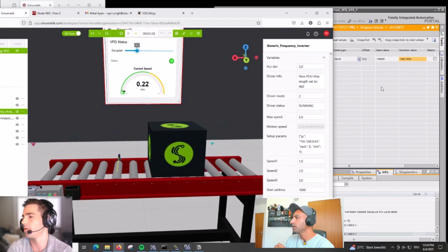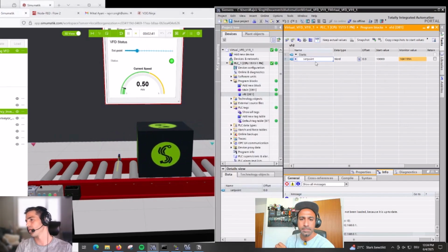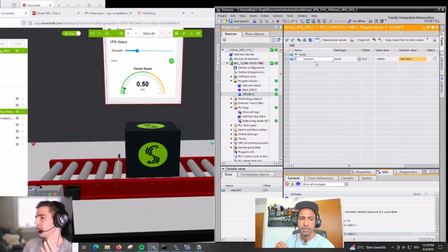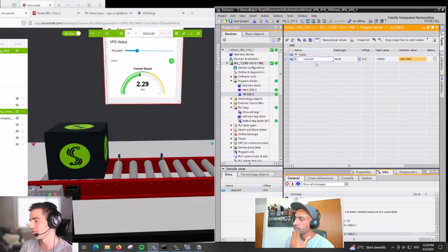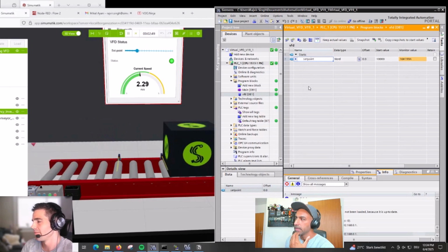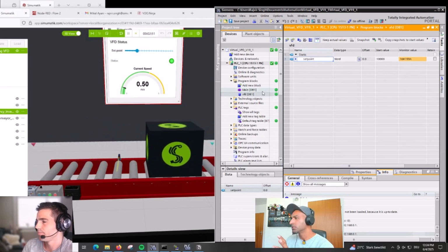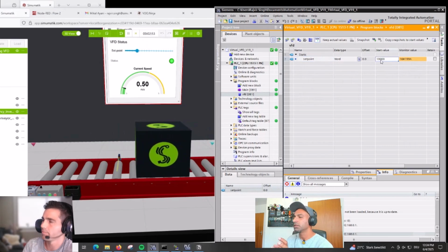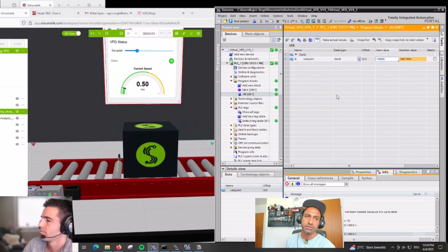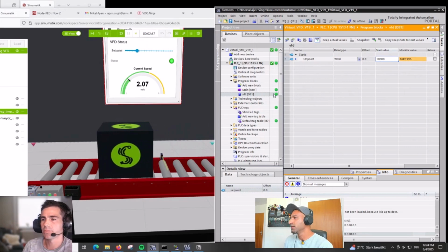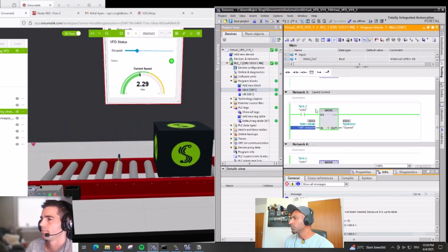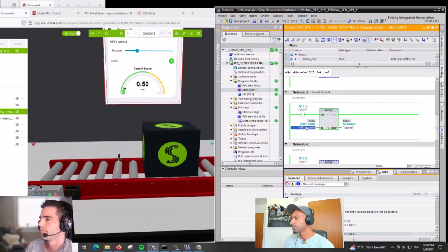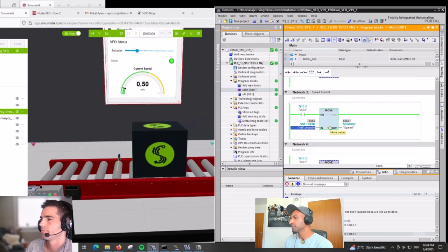So you are not setting the value in the PLC, in the code. You are just hoping someone writes the value. And in this case, it's Node-RED, which is set in the set point. Yeah, I just have a startup value. You can see startup value is 10,000. If nobody writes any function, it will have a default value. And this value then I just give here as a set point when the sensor signal is true, and it will change the speed.